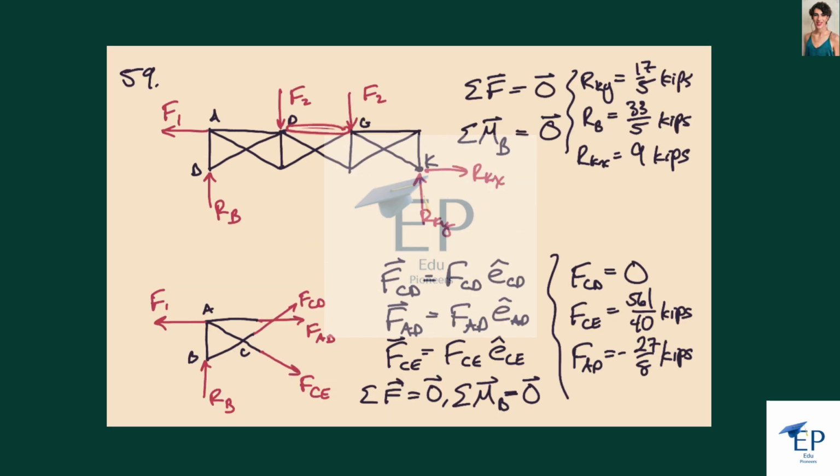So the stress in here is a lot more compressive than it is in here, and that's probably mostly because this force here is acting to stretch this member much more, and this stuff over here is carrying this load much more than this stuff over here. So we'd probably get a larger compressive stress in this member if we were asked to calculate it. It'd probably be lower than this, I suspect, but higher than this.